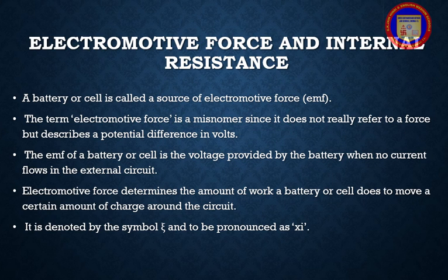Electromotive force and internal resistance. A battery or cell is called a source of electromotive force, simply EMF. The term electromotive force is a misnomer since it does not really refer to a force but describes a potential difference in volt. The EMF of a battery or cell is the voltage provided by the battery when no current flows in the external circuit.